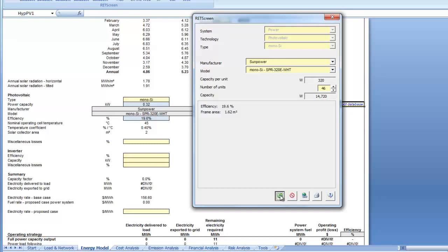At 2.5 kilowatts average capacities per electric vehicle, and 8 kilowatts for the potentially higher future residential loads, we would be at 13 kilowatts, which is the minimum before we get significant gains from the electricity exports. So we will initially size the system at 15 kilowatts, which will require 3 Orion carport structures.